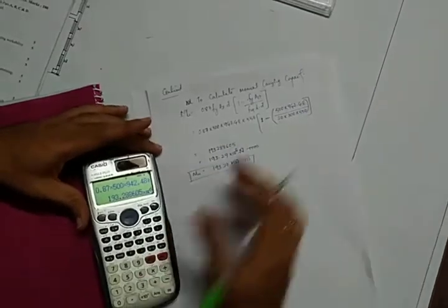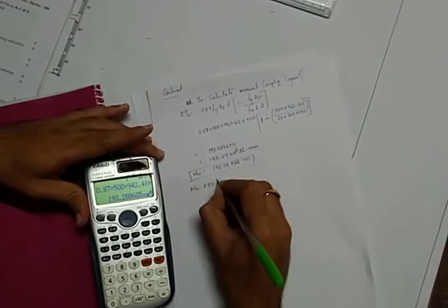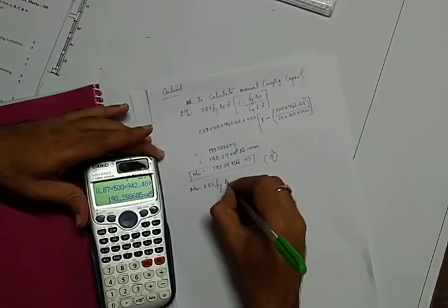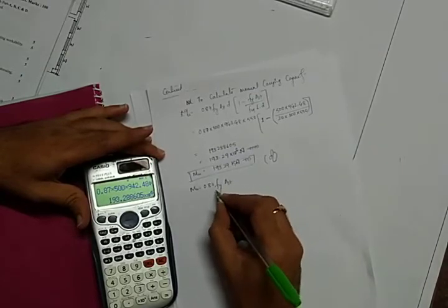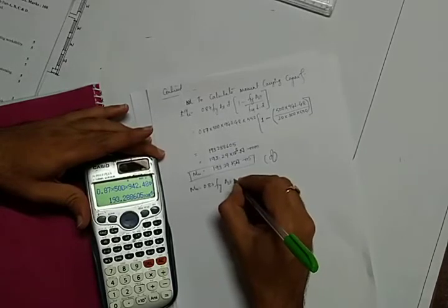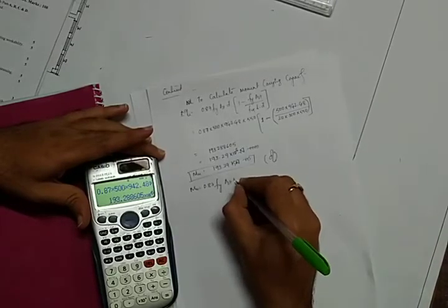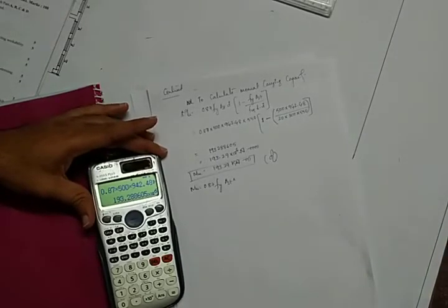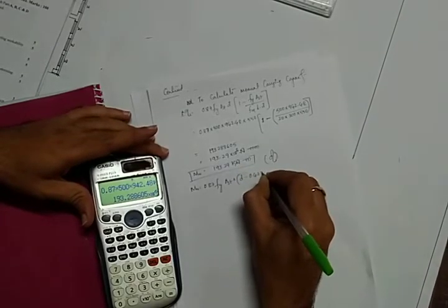Again, instead of this you can use another formula. I will write here itself, 0.87 Fy AST. So this is an option left to you. This is stress and this is the area, that is force into distance. Distance is d minus 0.42 xu.